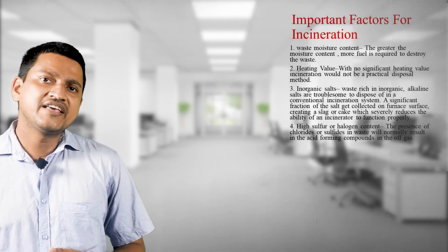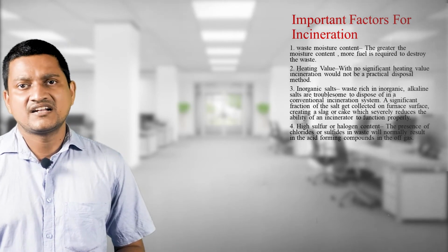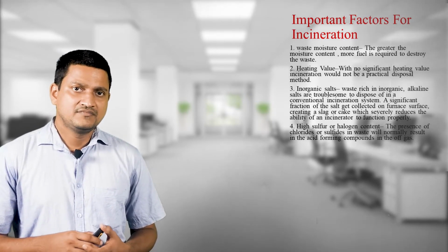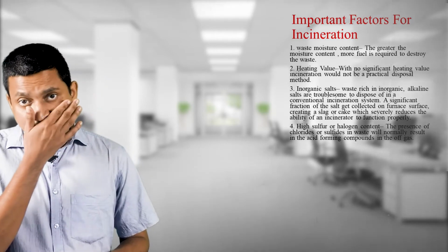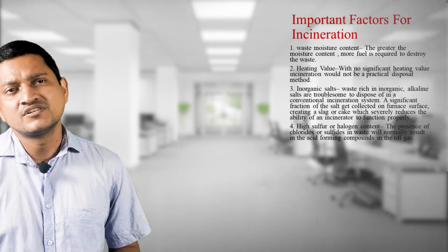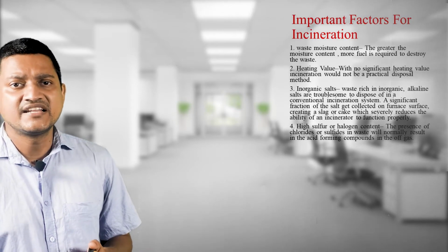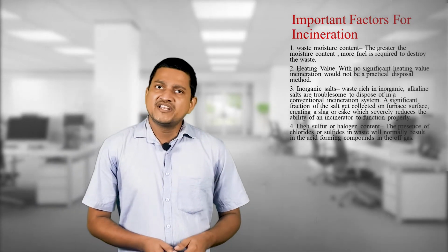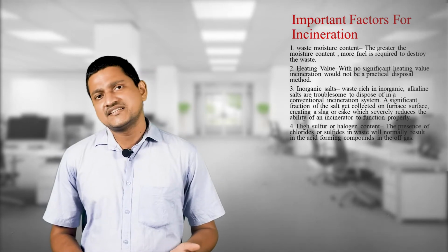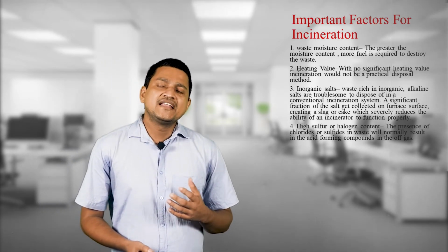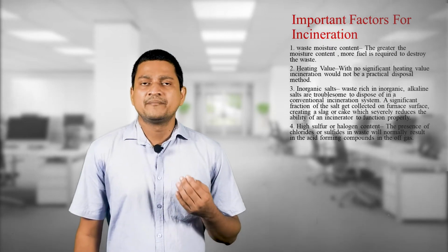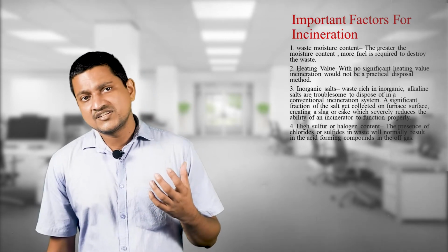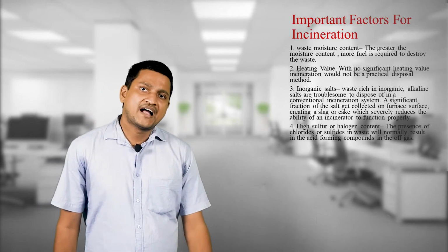Inorganic salt: wastes which are rich in inorganic alkaline salt are troublesome to dispose of in a conventional incinerator. High sulfur or halogen content: the presence of chlorides or sulfides in waste will normally result in acid forming compounds in the off gas. That will cause environmental issues. These are the major factors we consider when going for an incineration process. That is, the waste moisture content is measured, heat value is measured, presence of inorganic salt is analyzed, and high sulfur or halogen compounds should be analyzed.